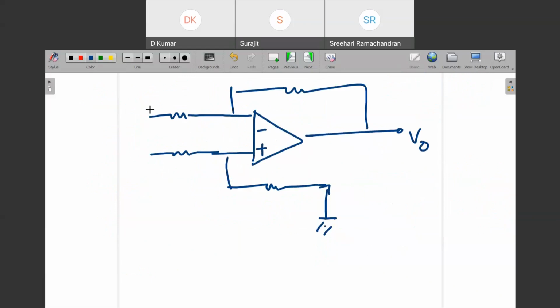The current here is going to this node, so this current will be divided in these two branches. What I'm considering here is 0 volt, because we always consider the difference between the two inputs of the op amp to be very small. So these 2 points are at the same potential. Understand? If 2 points are at the same potential, it means that they are in parallel.